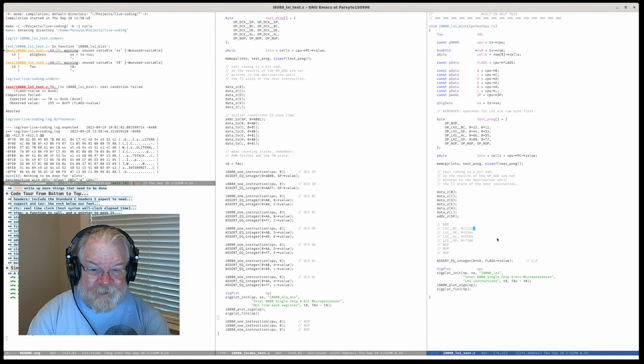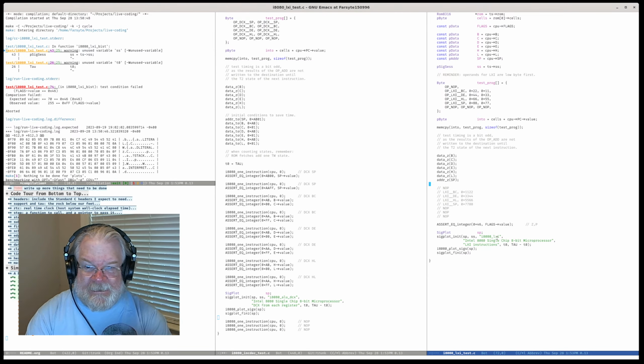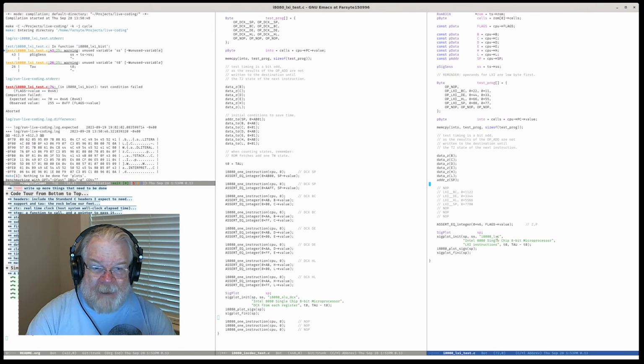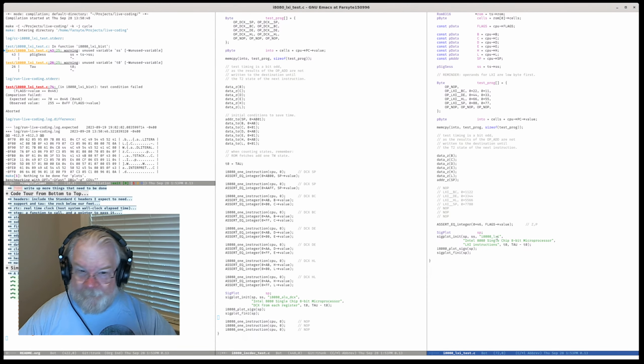Because when we write numbers naturally, in the English-speaking world at least, it is most significant to least significant digit going left to right. However, when we store data for the 8080, we store the least significant byte followed by the most significant byte, because the 8080 follows Intel's evil idea that you should put low bytes first, little endian. I am a fan of big endian architectures from the moment I saw my first big endian CPU, which I believe was the LSI 11.